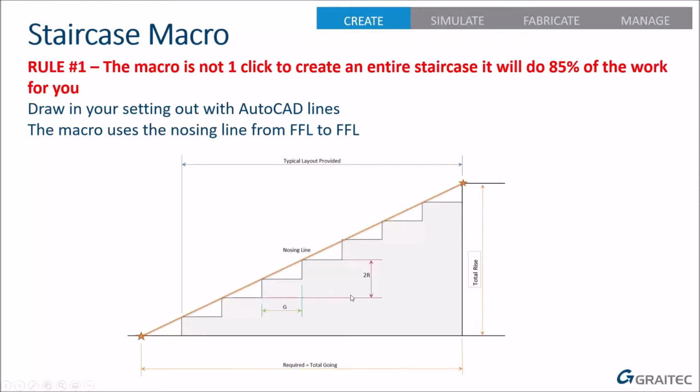There's a lot more to a stair than just the angle. You could have this stair at this angle, but if you only had 3 huge steps, it'd be really difficult to climb the stair, really uncomfortable. Or if you had the same angle, but with 100 little tiny steps, then again, you'd be on tiptoe trying to go up these hundreds of little steps, and it'd be really difficult to climb, really uncomfortable, not nice.